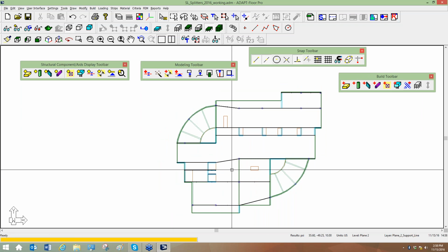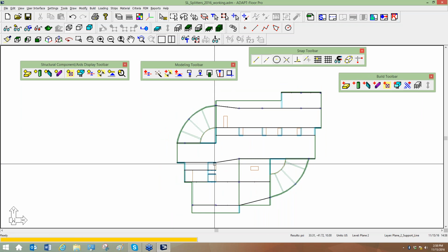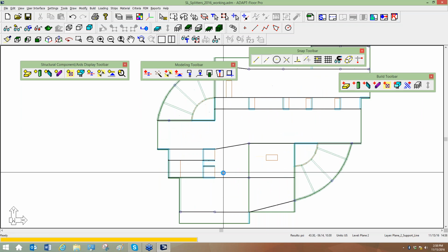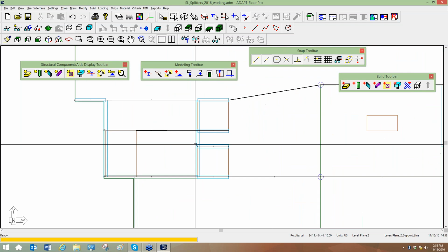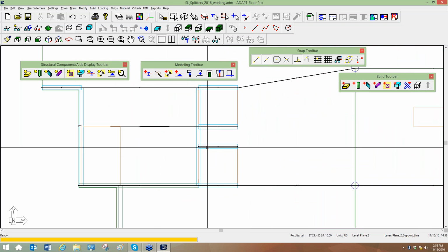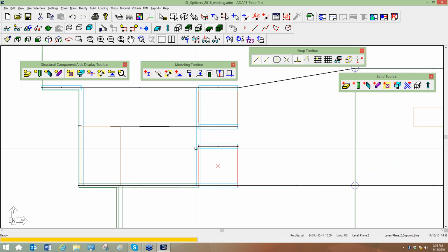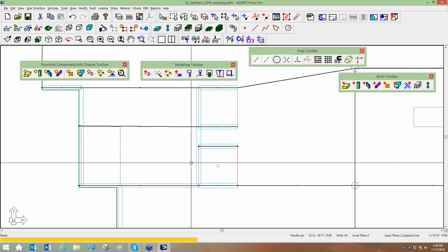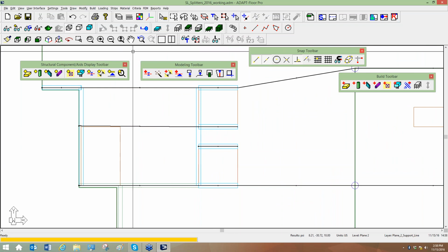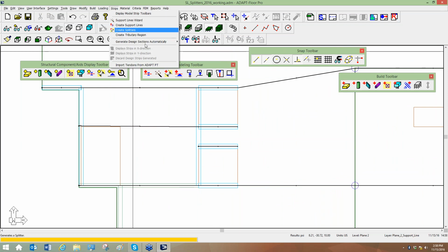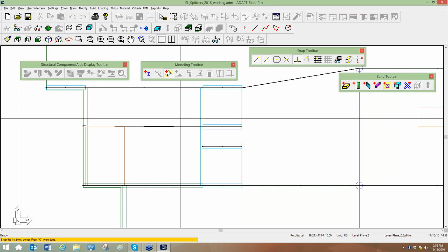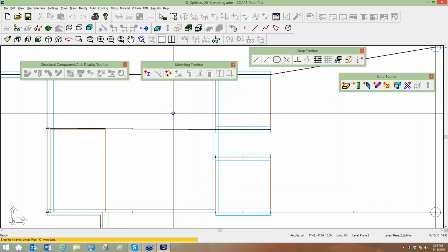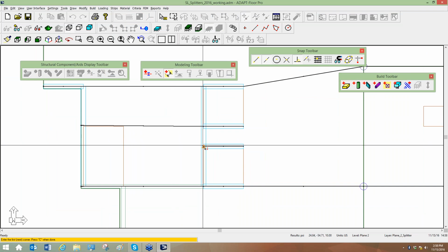We're now going to add splitters for this slab to refine our input. So the first rule of thumb, as I mentioned, we want to have splitters at support lines that terminate inside of the slab region. This is a good example, this support line here. Notice, by the way, that support line aligns with and is stacked on top of the opening. That's not ideal, but we'll manage to work with that. So I'll add a splitter. I know it's an X direction splitter without even looking at the assignment and the properties because it's a circle, so that's good. And I'm going to add a splitter from this point.